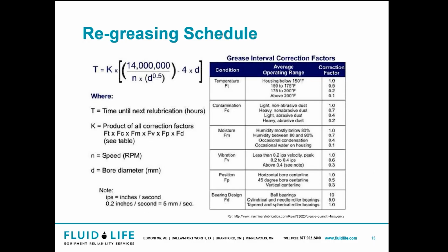So using a calculator like this, do not just re-grease a bearing every time you walk by it with a grease gun. A funny anecdotal story: we had a maintenance manager who was telling us that he installed all these grease zerks on a cabinet that led to nowhere, and he knew his lube techs were just greasing whatever with whatever.